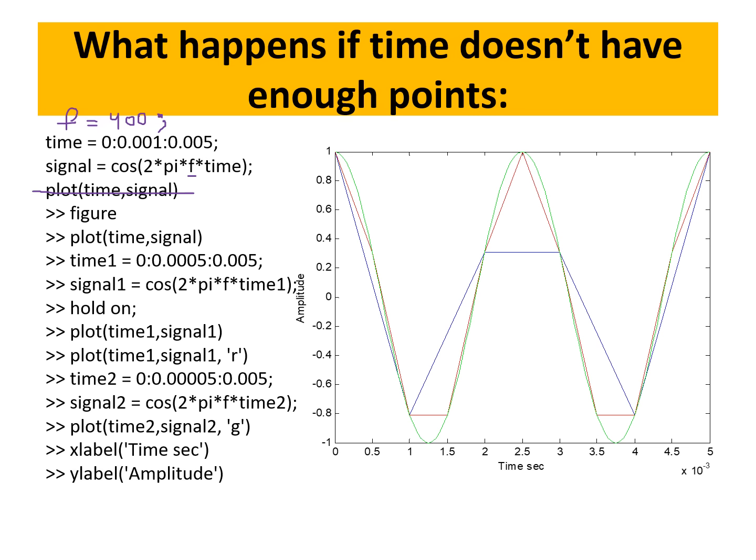Hold on, it's 6, because it starts at 0: 0.001, 0.002, 3, 4, and 5. So 6 points, which is a very, very small number of points to get the data. So it's not even a sinusoidal, you can tell. And then you did the figure and you plot the figure. And that's the importance of sampling. If you are not getting enough points, you're losing the signal, and we can't reconstruct it and make sure that it's what we would like it to be.